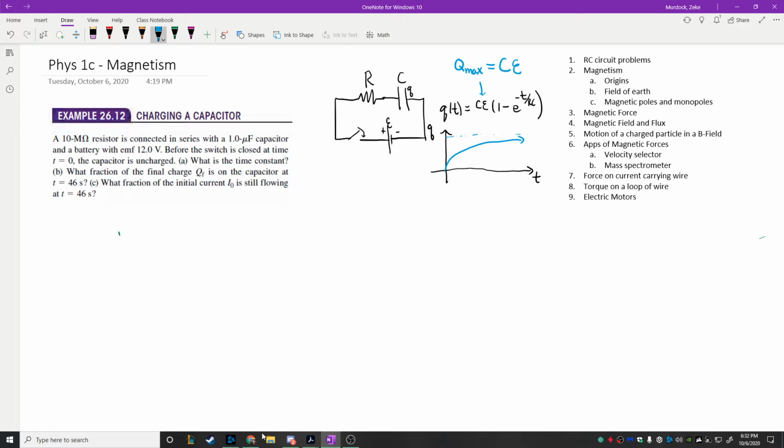And one other thing to add was that there's a time constant that we define for the circuit that's called the RC time constant, and often the symbol tau is used. And it's equal to the resistance multiplied by the capacitance. And what we learned is that this is the time that it takes, so this would be right here, t equal to tau, for the charge on the capacitor, or the voltage across the capacitor, to reach about 0.63.